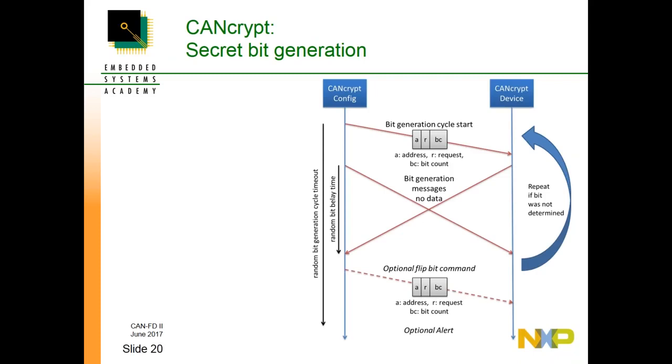Let's look at the key exchange. At some point, devices in any secure communication need to exchange some keys, and this method is based on something that Bosch already introduced quite a while ago at one of the earlier international CAN conferences, and they did it in hardware. However, that would require yet another CAN controller where this is implemented in hardware. So we took the basic methodology behind it and do it in pure software and in pure messages, so no hardware changes are required.